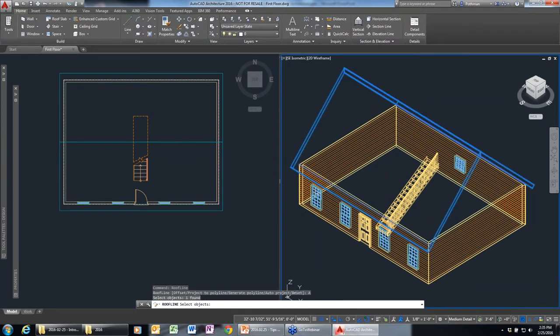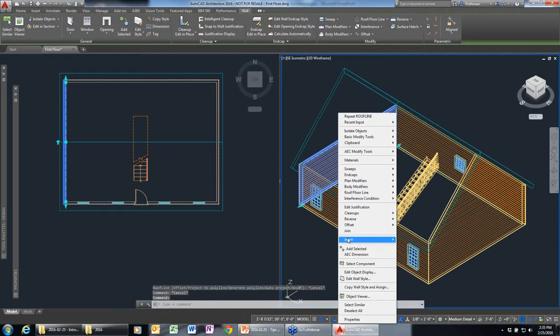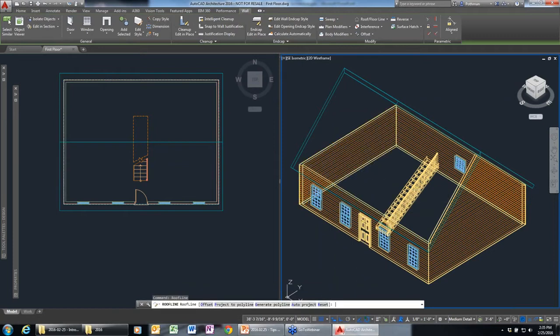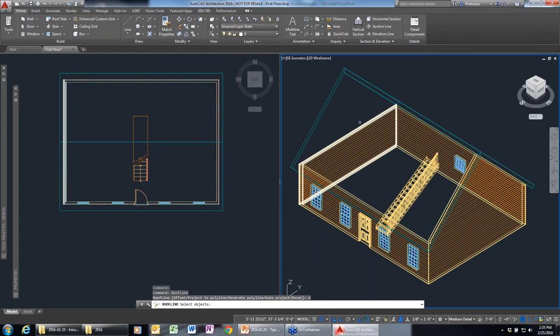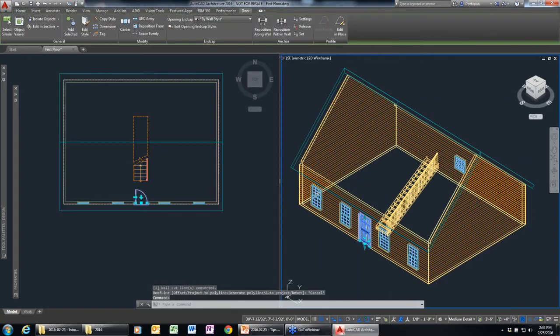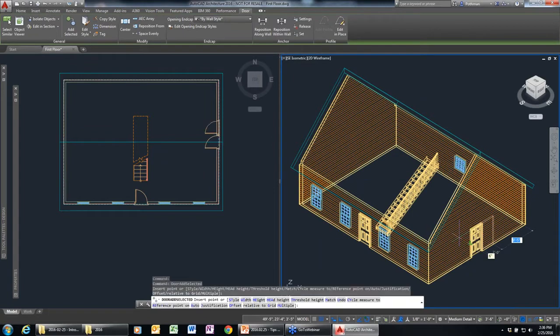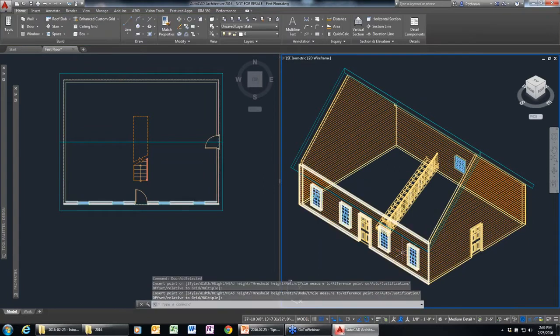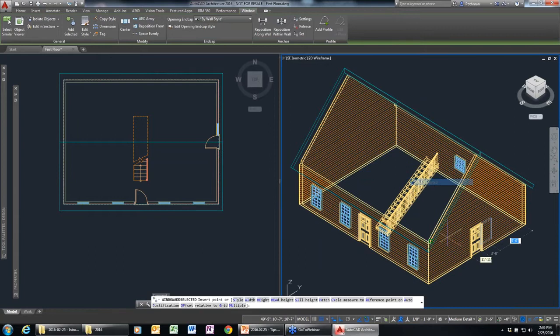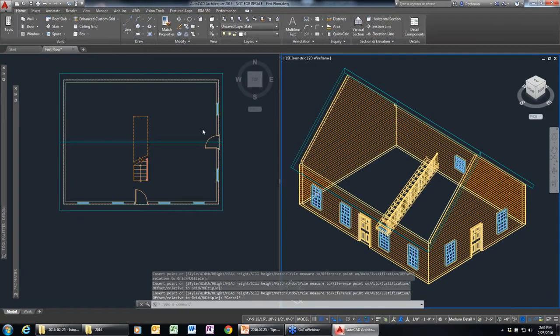And you can see what happened here. I do the same thing over on this side. I'm going to go to roof floor line, modify roof line, auto project, and pick on the roof. And I now have that whole side of the building filled in. Let's add another door. Why not? Let's do add selected, and we'll just put a door in over in that direction. And maybe I want to add another window over here, so add a window there and there. And you can see you can work in plan view just as easily as you can in a 3D view.